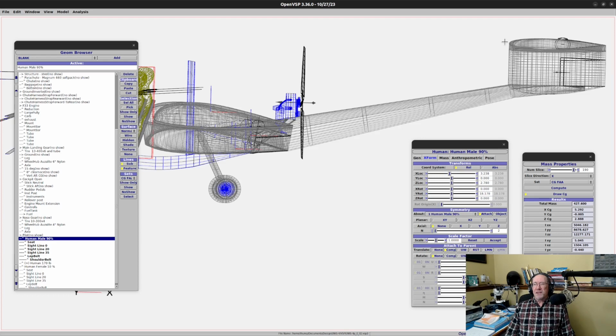And this horizontal tail is not going to come any farther forward, because the 30-degree angle coming off the trailing edge of this wing determines how far forward I'm going to be able to make that horizontal tail, because in a spin, I don't want the horizontal tail to be blanketed. From 30 degrees from this trailing edge to 60 degrees from the leading edge, that's all kind of blanketed. That's kind of a rule of thumb that you don't want to have your horizontal tail anywhere in that blanketed area from the wing if you're in a full stall, full spin. You still want to have that horizontal tail to be effective. So it's not going to come any farther forward. So for the most part, the position, at least of this leading edge of the tail, is not going to change. Size of it may change.